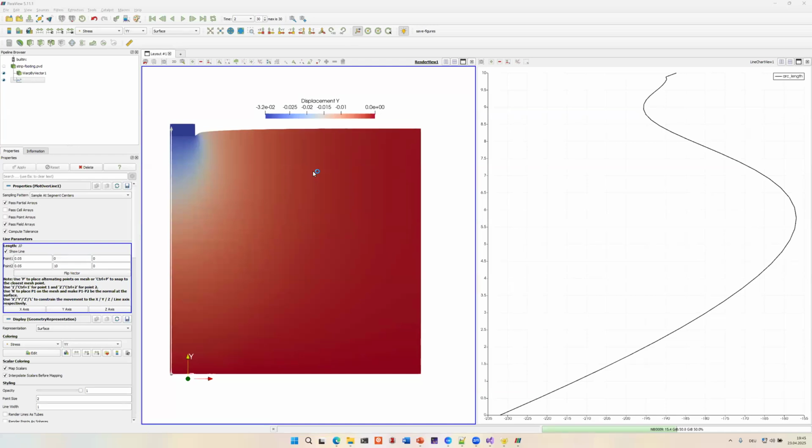So what you could do is you could just start a simulation, and then the mesh will automatically be updated in order to have a good mesh quality throughout the entire simulation, even for large deformation like runout simulations or dynamic compaction or things like that. So what you could currently do is, obviously you could always cut your simulation in smaller parts and then perform some sorts of mapping of the states, right?